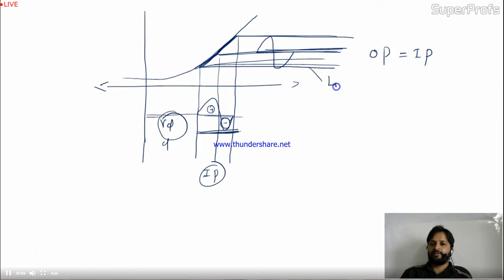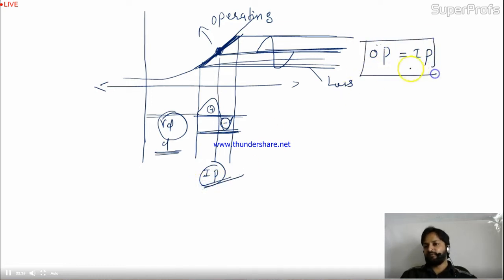There will be no loss in this condition, if you have chosen the proper point appropriately. This point we call the operating point. Later we'll discuss it. But this is kind of, we are adding some DC part into the small signal or AC signal, so we can shift the level. If we can shift the level, the signal comes to this linear region, and once the input signal is in the linear region, the input output mappings are equal to each other. Is it okay?